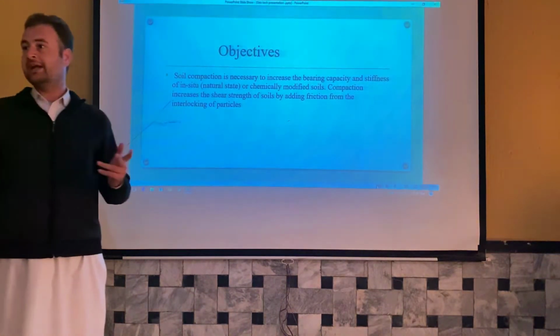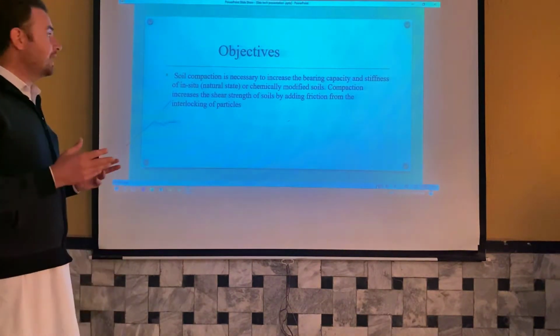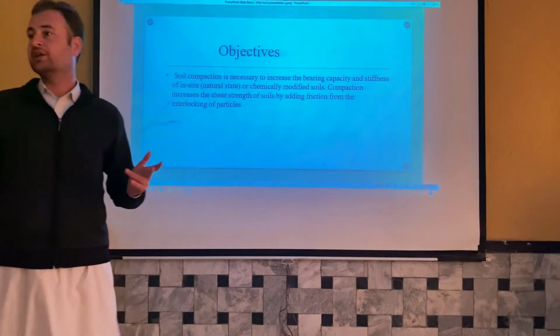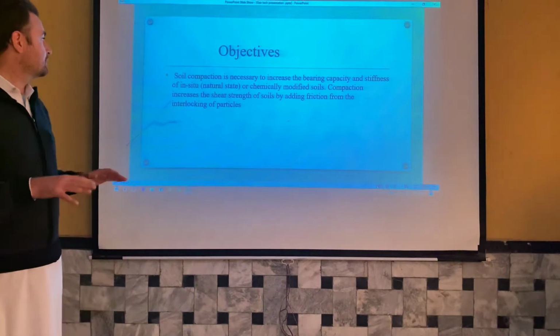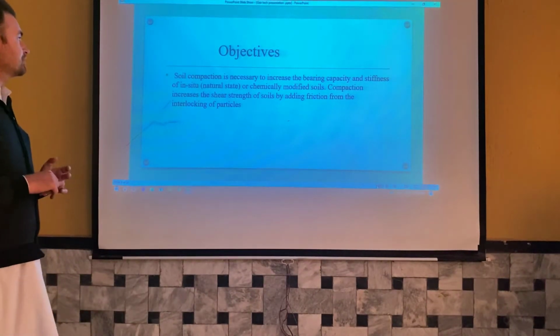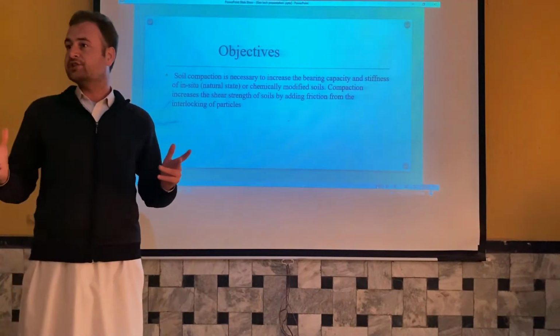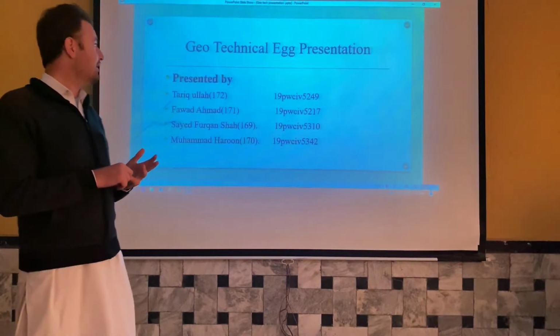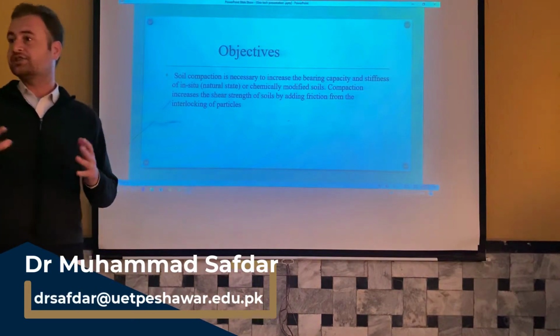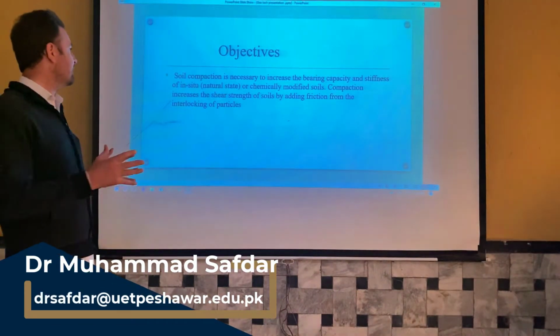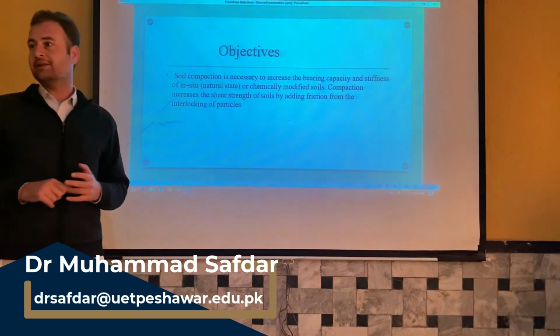This is a very broad topic and is used in a lot of projects like embankments, roadways and all the walkways. So this is very important. Soil compaction is very necessary. It increases the bearing capacity of the soil and the stiffness. So in that way, it is very necessary for all projects.